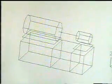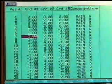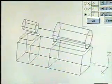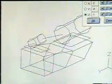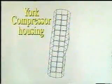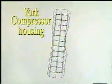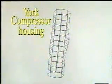Make a grid sketch of the machine locating the specific points for making measurements. Record the phase readings for each of these points. The operating deflection shape can then be animated and turned to see how each element is moving. From this, you can get an idea of the flexing taking place in the machine. Static phase measurements can provide much information about the machine's condition, and when multiple phase data points are input into a software program that animates the data, you can actually see the movement that is taking place in the machine.